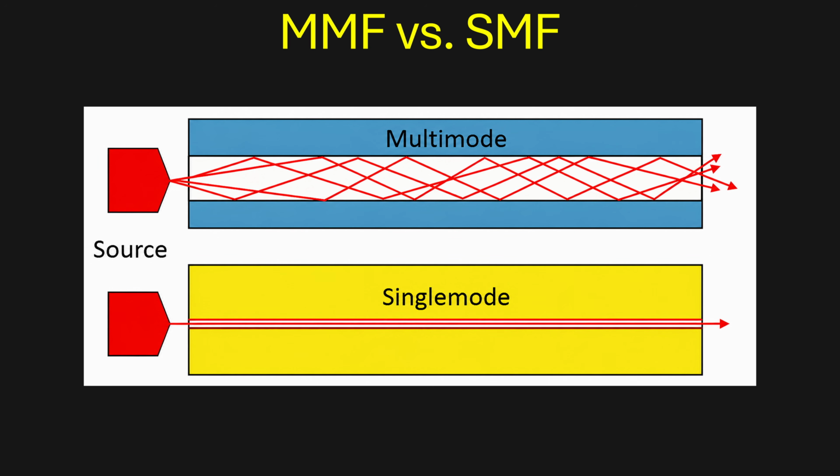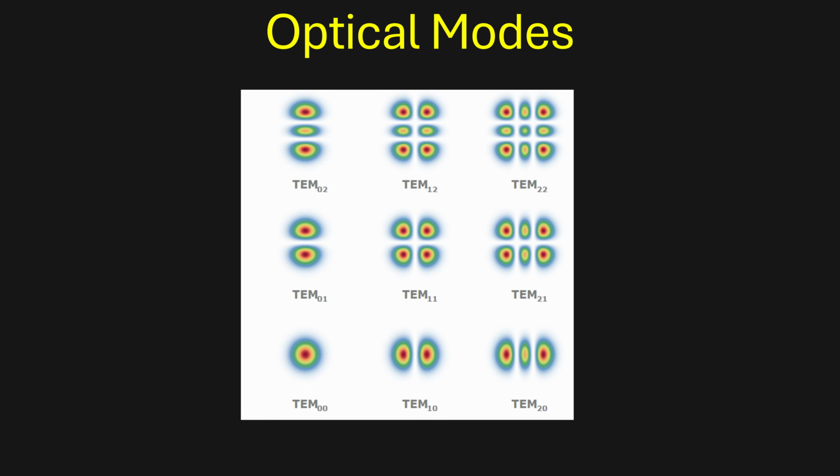Optical fibers can be split into two main categories: multi-mode fiber and single-mode fiber, with multi-mode used for short distances and single-mode used for longer distances. Single-mode fibers are smaller and transmit a signal with a single transverse mode of light, while multi-mode fibers transmit the signal on multiple modes. Transverse optical modes are electromagnetic field patterns of photons that the optical field will produce. In fiber optics and lasers, light will be described using these field patterns instead of individual rays or photons.